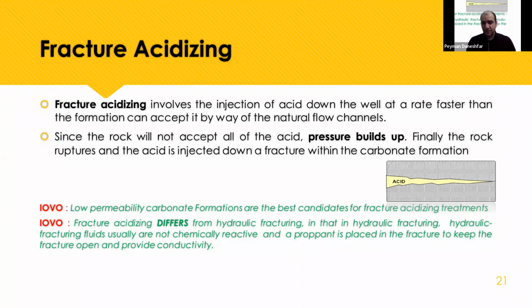And one thing I think you should know here about fracturing and fracture acidizing: hydraulic fracturing is different from fracture acidizing. In fracture acidizing, we use the acid to open or create fractures by dissolving the rock in a carbonate formation.